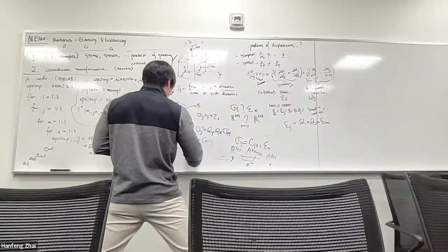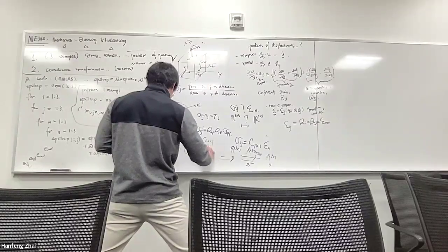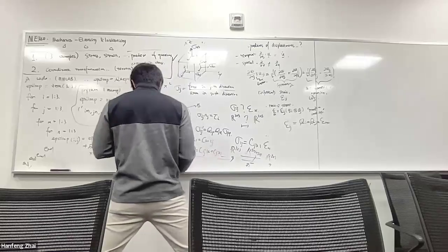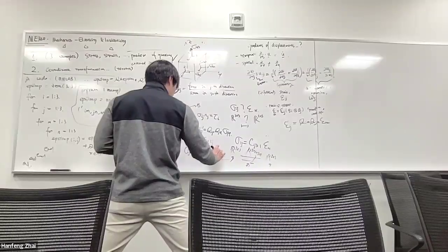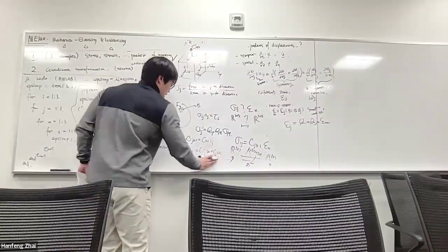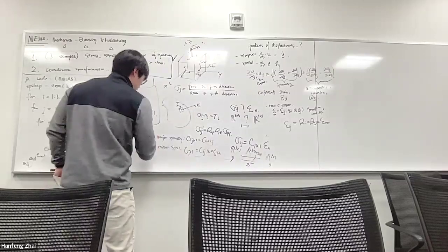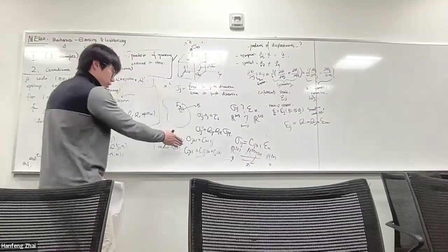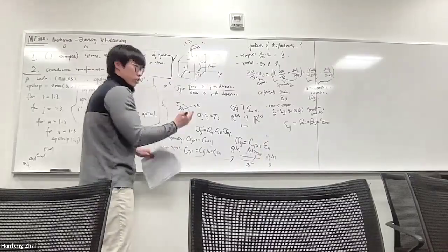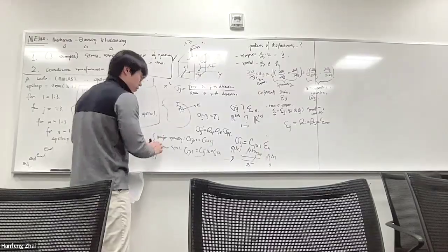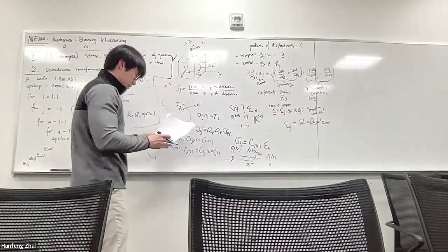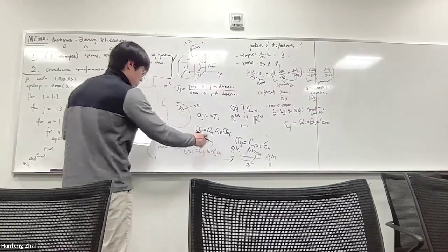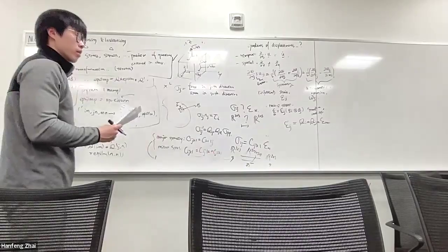So Cijkl equals Cijlk equals Cjikl. After applying the symmetries of the elastic constant, which later you will understand to justify why it's like that physically, but for now you just trust us, it can be reduced from 81 to 21 components.